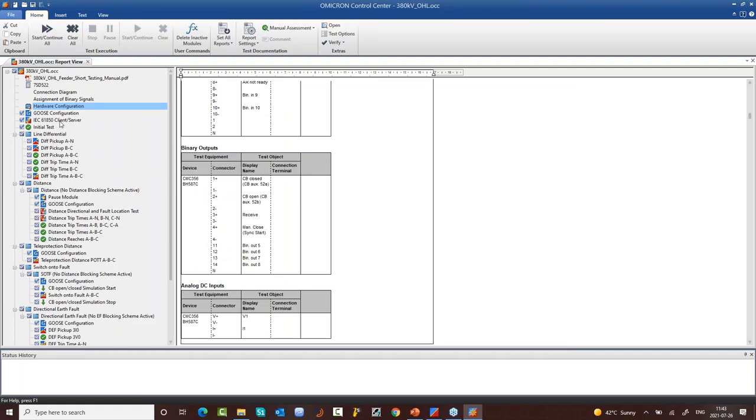My first test module actually is to make a wiring check. This is very, very important to consider, this module or this step, before starting the testing for your relay or your device. Because if you have a problem in the wiring, that means you are wasting your time in this testing. How I do it, actually, the basic thing is to inject 3 different voltage values, 3 different current values, and during the injection you have to go to the relay and read it out.